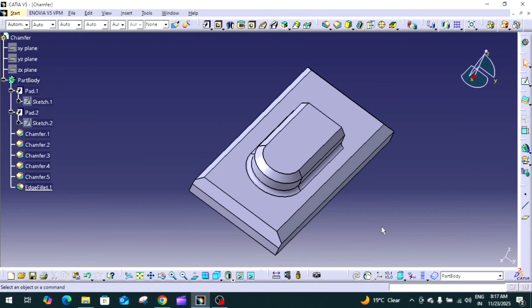You have to keep in mind these 4 points always, so that your chamfer does not fail. Or you can try a smaller value, reduce edge selection, avoid overlapping chamfers, or apply the chamfer step by step.